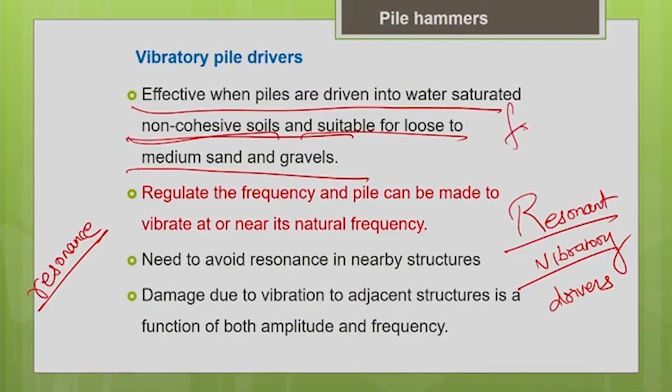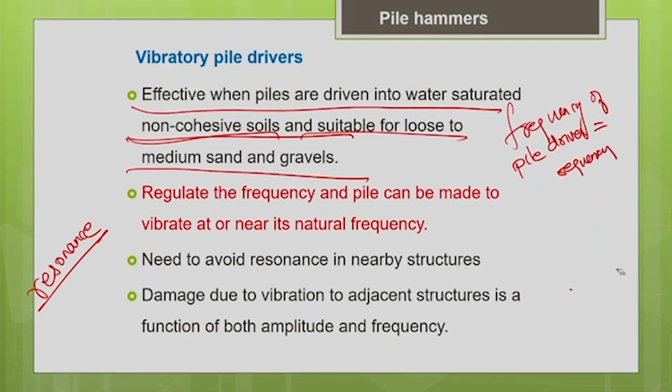So, you match the frequency of your pile driver to the natural frequency of your pile. You have to estimate the natural frequency of the pile depending upon the mass, stiffness and length. So, you adjust the frequency of your pile driver to match the natural frequency of the pile. Now what happens is it results in the condition of resonance, so it will result in huge displacement of your pile. So very easily you can drive the pile into the ground.